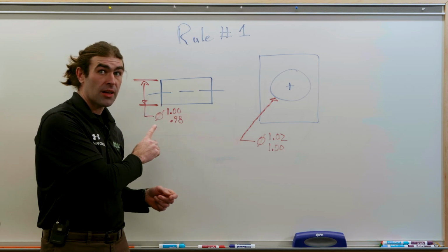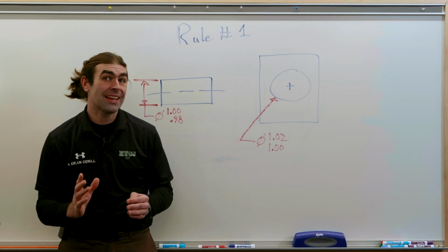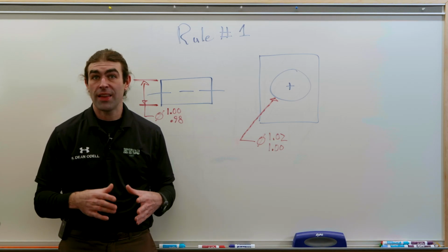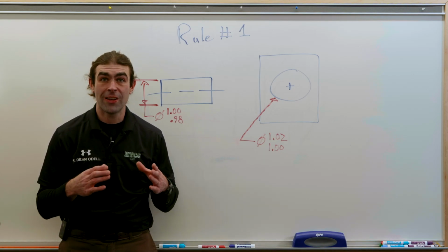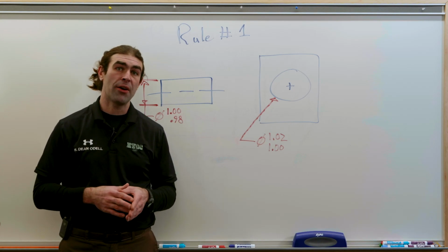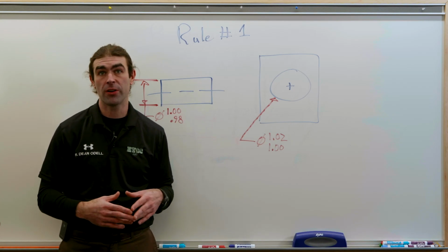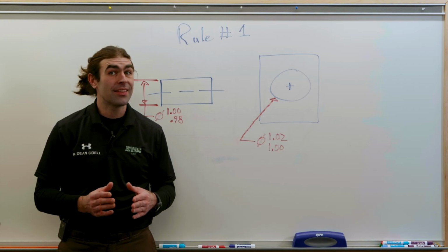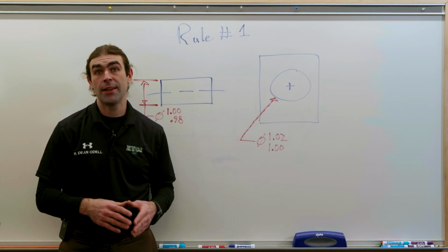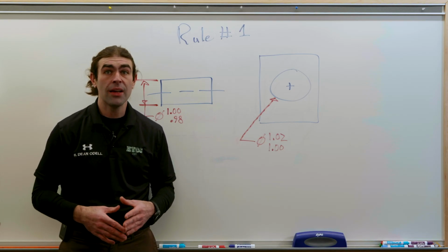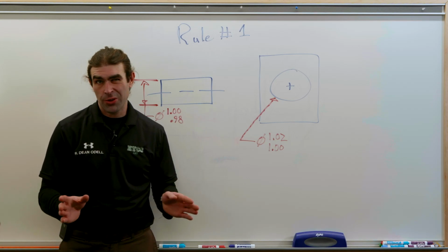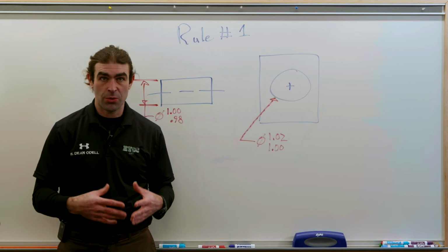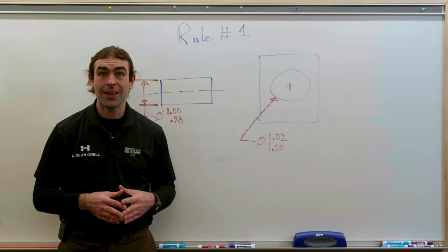That would reject a couple of good pins. Or the gauge could have the tolerance on the outside of the hole, so the hole could get bigger. That would allow the gauge to accept bad parts some of the time. This is known as optimistic and pessimistic gauging. Now, we can really not worry about that right now. That's really specific to inspection.